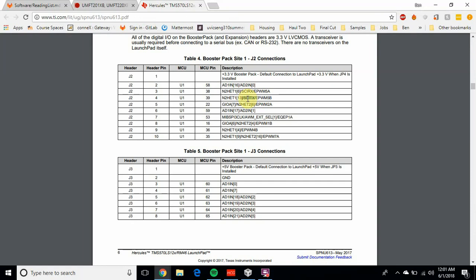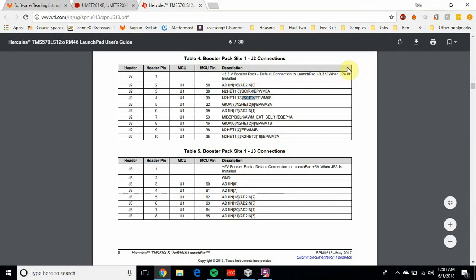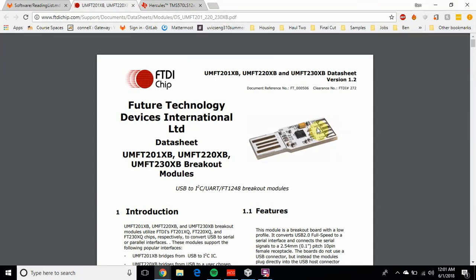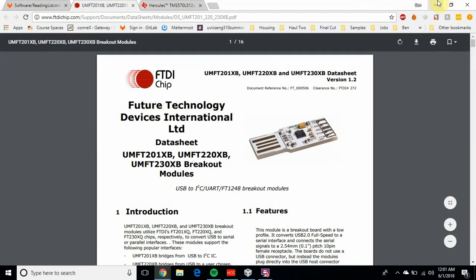So now that you've set up the hardware itself, just to reiterate, you have those 3 wires coming from the breakout board, so TX, RX, and ground, into TX, RX, and ground in the board, as well as the USB cable from your computer to the board itself, so you're able to actually pass information in terms of flashing the code to start, as well as power the board. Those are the 4 connections you should be establishing right now.